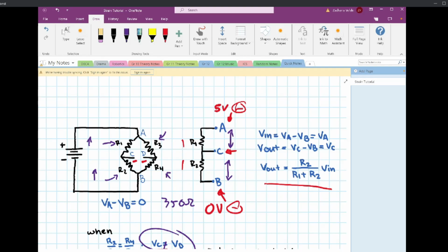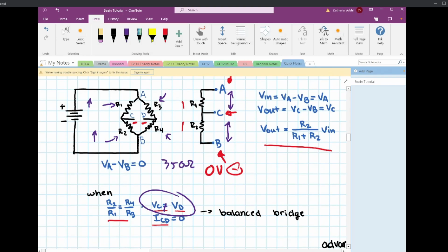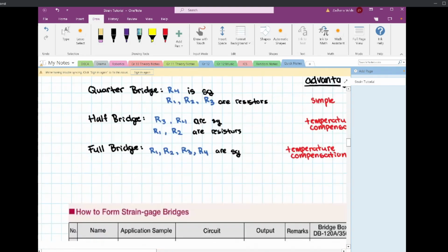And this also makes the most sense if you're doing anything less than a full bridge. So if you're doing a quarter bridge or a half bridge, for quarter bridge you're only dealing with 2 wires coming off of the tube, and for half bridge you're dealing with 4, which honestly isn't that bad. And if you're doing either of those, then you're going to already need to use dummy resistors somewhere anyways. So you might as well only take off 2 or 4 wires.